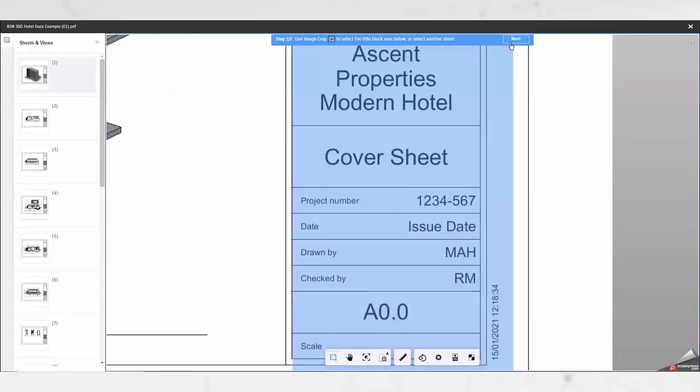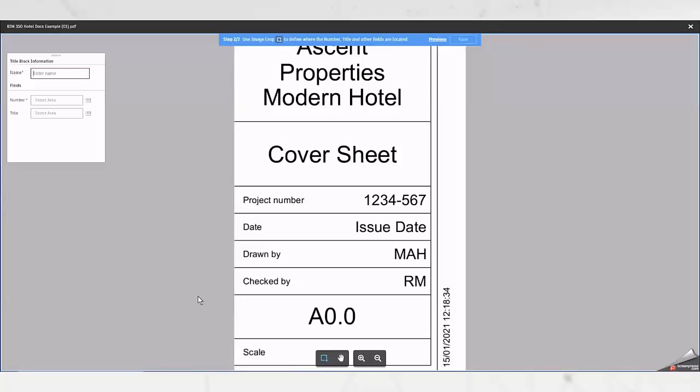We'll then OK that, and then it gives me a list of parameters that are available to us. So the block, I need a block information name. There'll be a number requirement, as you see in the first one, which is the only required field actually. So if you've got a drawing number, you're good. We can change the orientation should we need to on that. So for the right-hand one, but it's quite good at sorting them out if it's wrong.